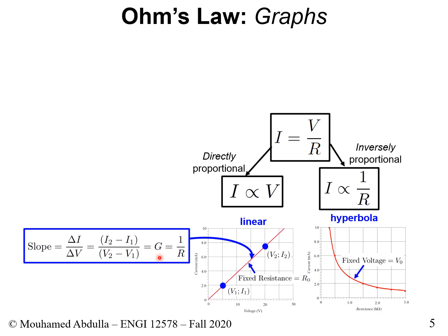And G, we talked about it before. G is simply the conductance. And if we know the conductance, right away we can determine the resistance. It's just 1 over. So anytime you have a current versus voltage plot, if you find its slope, the resistance will be 1 over that. So it would be resistance is equal to 1 over the slope of an I versus V plot.